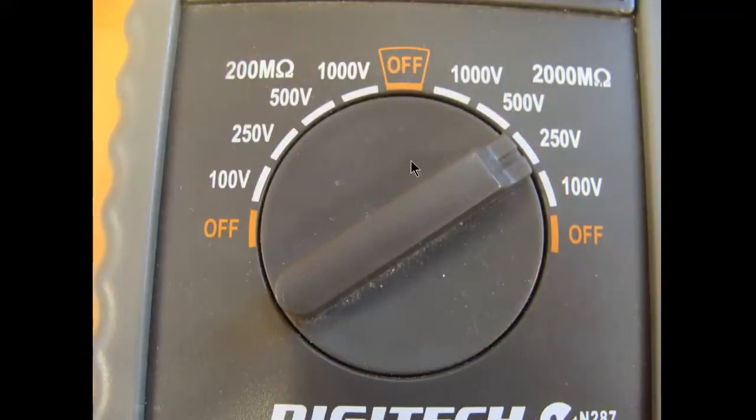We can also use it on a low voltage, so 250 volts, or we can try and short out the diodes internally inside the equipment that we're testing. So if they're shorted out, there's no danger of voltage going across them and blowing them. So 3 ways: short out the phase and neutral, reduce the voltage to 250, or bridge out the diodes within the equipment.